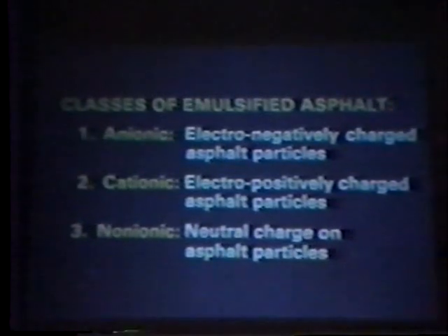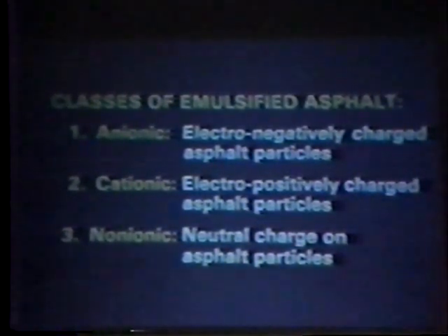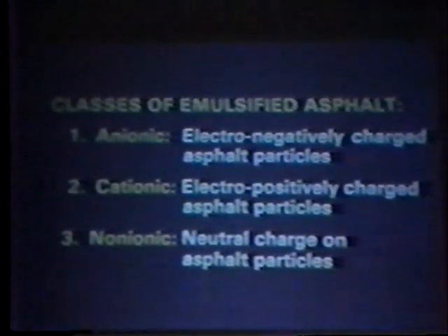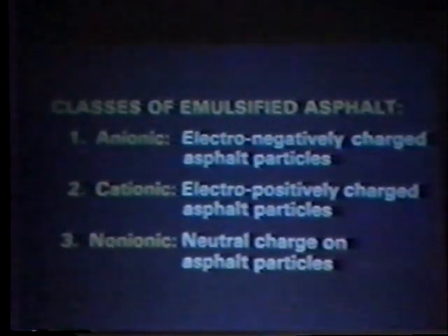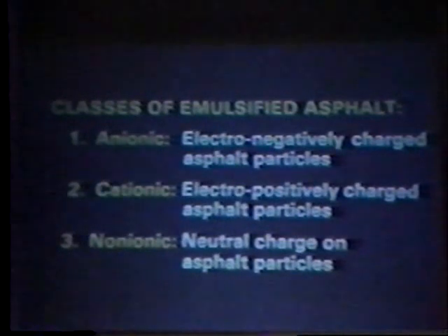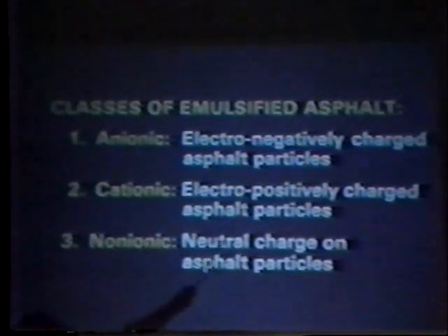Now, sometimes I think that the whole progress towards using emulsions has been held up simply by the way that they've been marketed in a proprietary way, and the fact that they use so many different emulsifiers for them. It creates so many grades and brands, it confuses people. And one thing we have to point out is that in the emulsion grades, there are two types. One is negatively charged because of the kind of emulsifier they use, and they call them anionics, and the other is cationics, and they're positively charged.